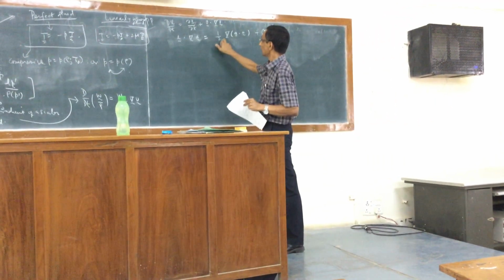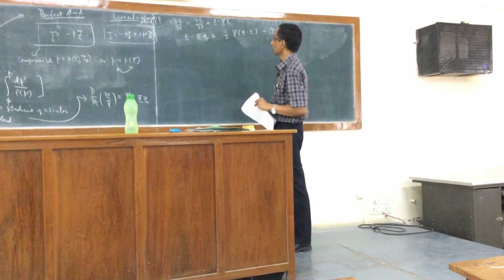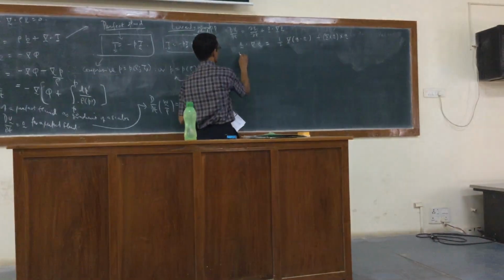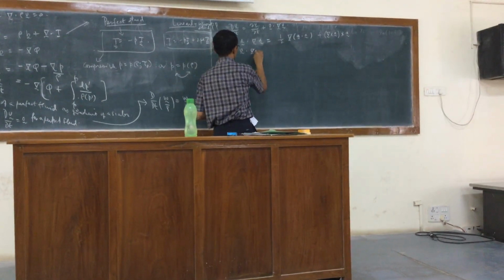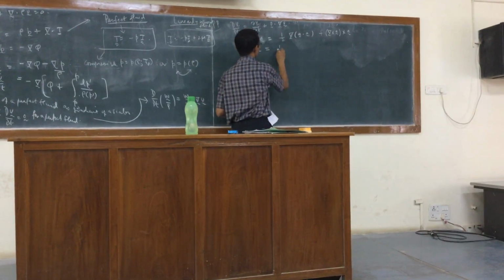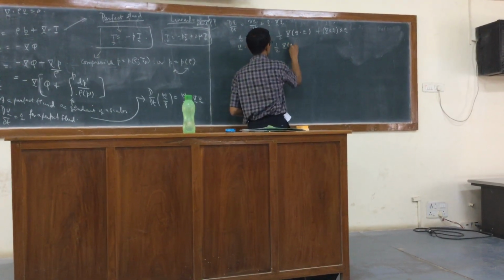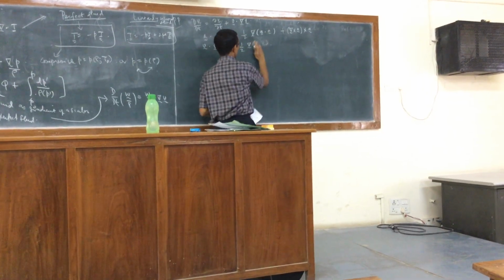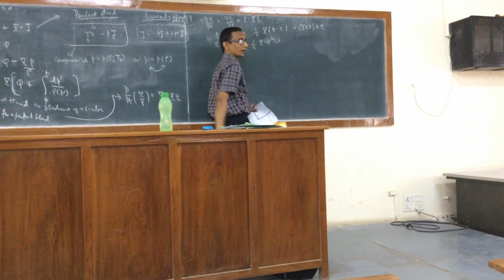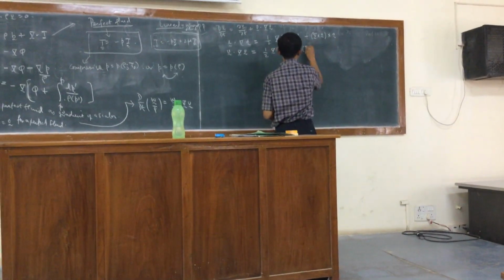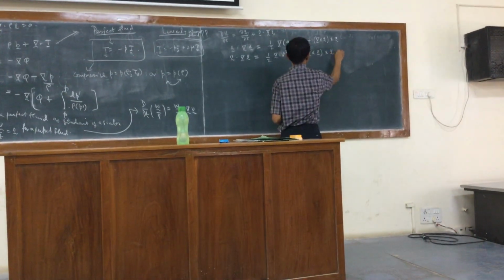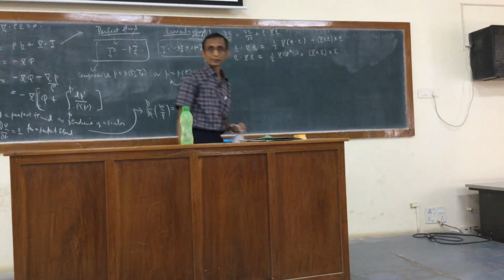So, in this equation, if I now apply it to V, I get V dotted with the gradient of V is equal to half the gradient of V dotted with V, which I can write as V squared, plus the curl of the velocity cross the velocity.